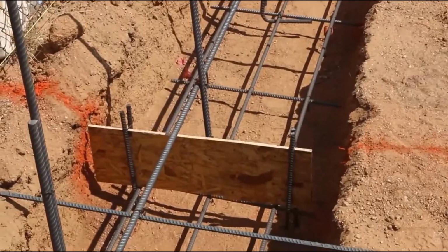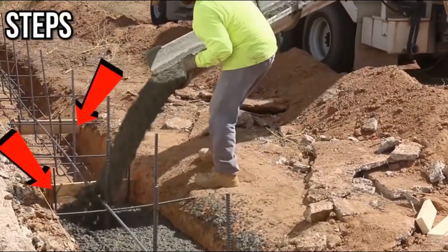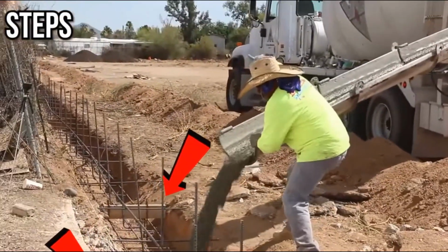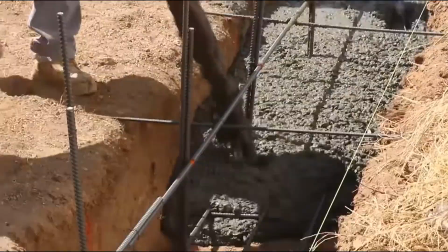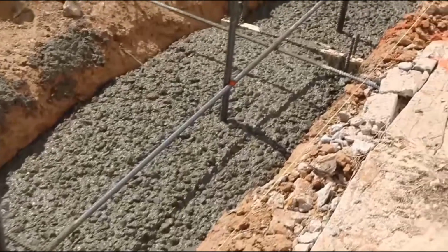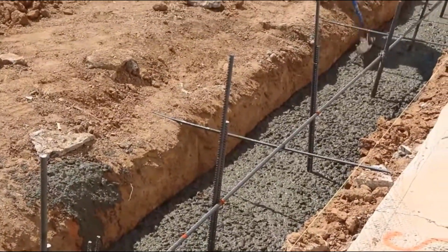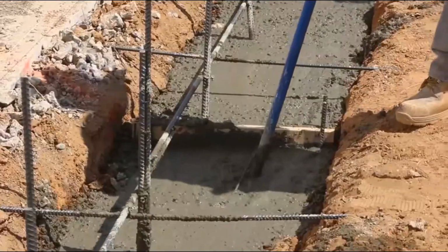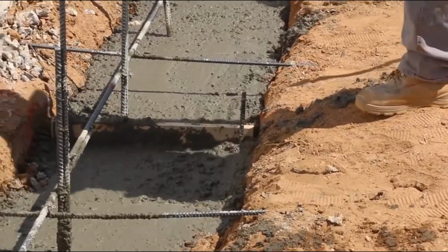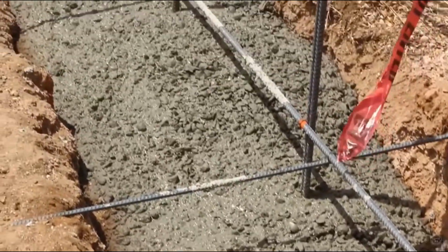So as they were digging these footings, they had to step the bottom elevation of the footing and then put a little bulkhead in to make a step at the right location, so that the top of the footing also stepped, always remaining level, so that the base course on the wall could be level and the wall itself would be appropriate. So level is important. Steps are part of figuring out how to do the preliminary work for the block wall.